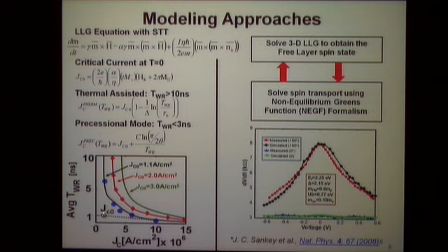The important thing to remember here is that most of the write times in this graph are between 1 and 10 nanoseconds. So it's a reasonable assumption to make that switching times in these devices would be on the order of 10 nanoseconds. It's very difficult to get it below 1 nanosecond because of a whole lot of physics involved in this. So we are not looking at something which will be a drop-in replacement for SRAM. It's going to be much slower than SRAM for sure.